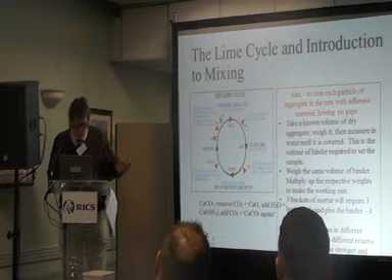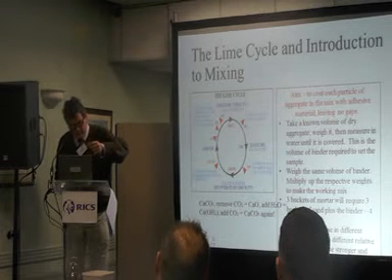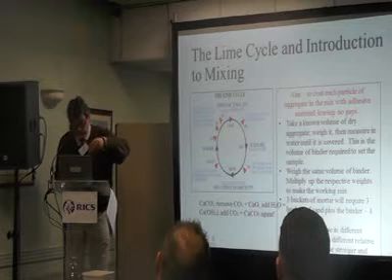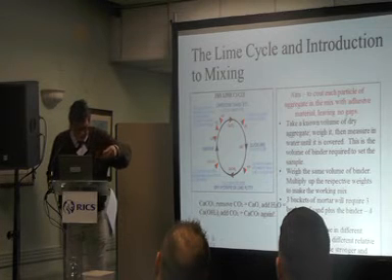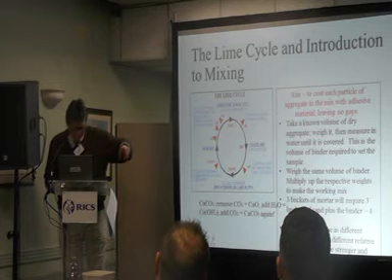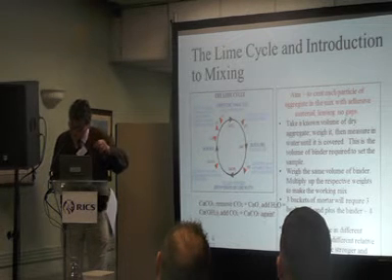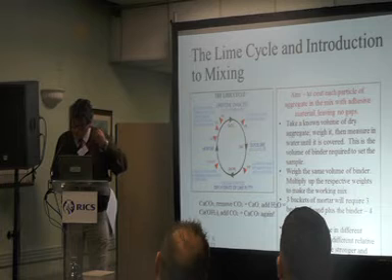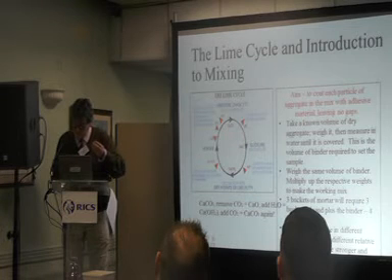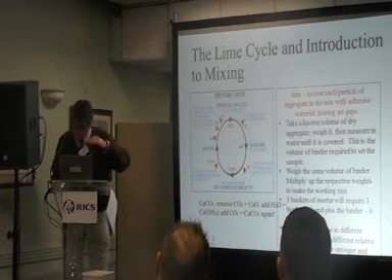Now that slow process is the carbon dioxide coming back into the lime, chemically rebonding. So, having gone from limestone through these processes, you come back to CaCO3 once more. Chemically, it's the same. So it's the perfect cement. You've got limestone back in all the joints that are bedding your building.